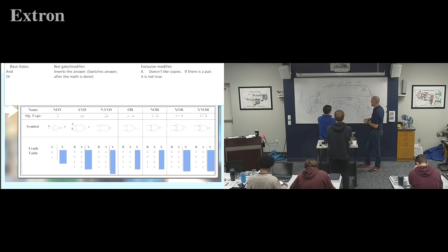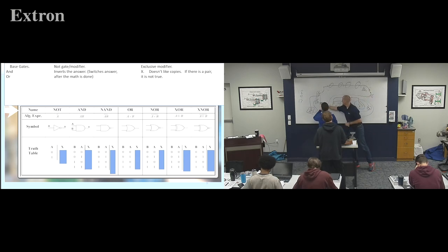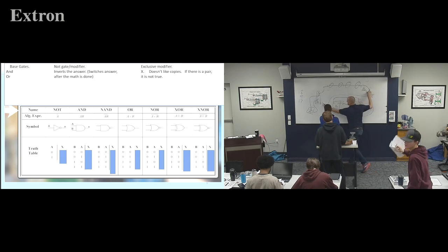So we're not gonna lose any voltage across the wire. It would be 12 volts. Yeah, correct, yep. Now what about if you take the voltmeter here and there? Isn't that what we just did? There's no resistance. Oh, sorry, I thought you meant there. Okay, so here to here would be 0.